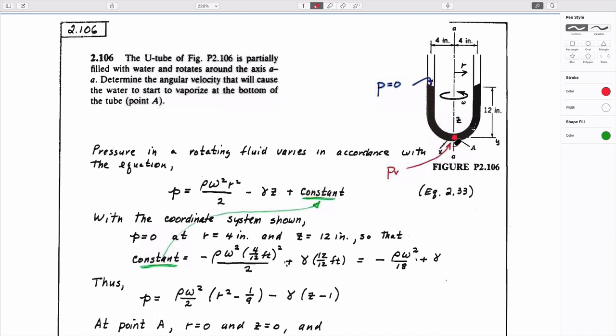And so if the tension is enough that it cavitates, boils just due to a pressure change, but not due to a temperature change, then you'll get an air bubble forming here. It's one way that you can de-air water, by putting stuff in a siphon, taking it up. How many meters would it be? Well, it's 10 meters, right? 30 feet. Take it up over the top of the siphon and back down the other side. Atmospheric pressure here, almost a vacuum at the top, and it takes all of the air out of it into a bubble, and you can collect it.